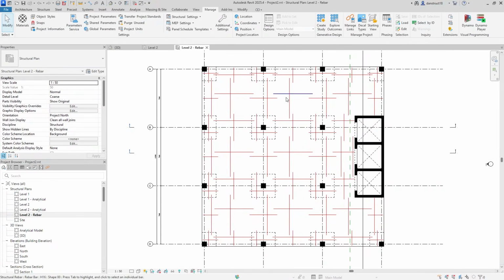We're going to use a special detailing technique for this video, where we have the bottom reinforcement and U-bars on one view and the top reinforcements and U-bars on another view. So the U-bars will show in both views, but the top and bottom would be in different views. The reason why we've decided to take this approach is that we might have a lot of bars and they can clash with each other. There's also another way where you can group them, but I always advise that you do it very detailed, and then you can also read it on site.